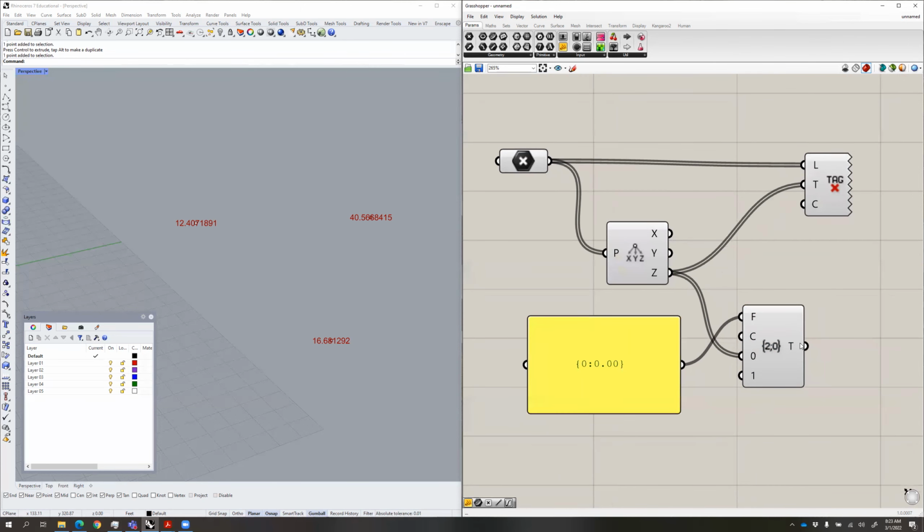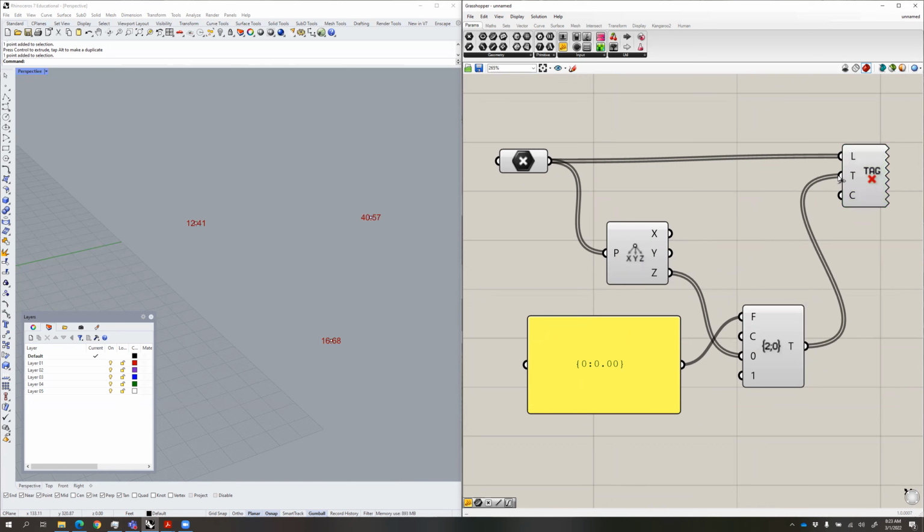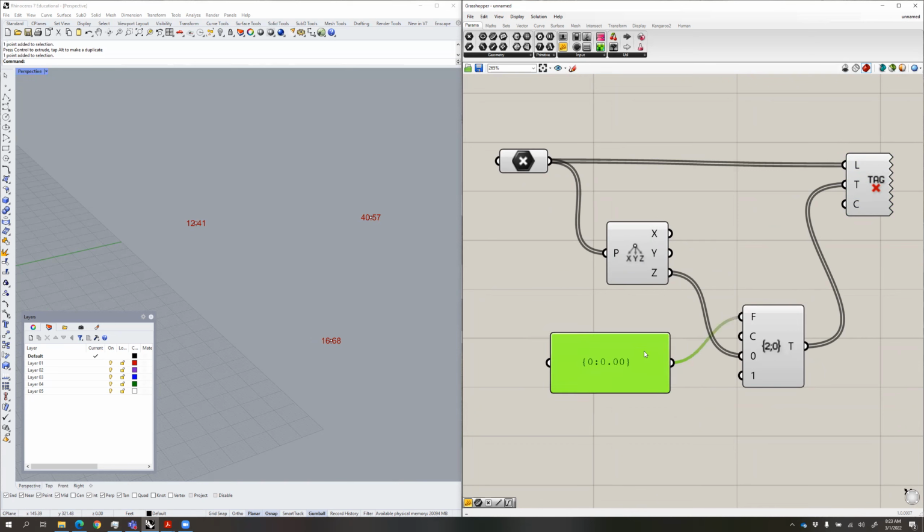And then if you plug that into the new text string there, you see what happens is now that spot elevation has been rounded to 2 decimal points, which for construction purposes is pretty much the only precision you need. You don't need any more than 2 decimal points usually for spot elevations. So that's a nice way you can take that number there and format it to be more landscape architecture friendly, I guess we can put it that way.